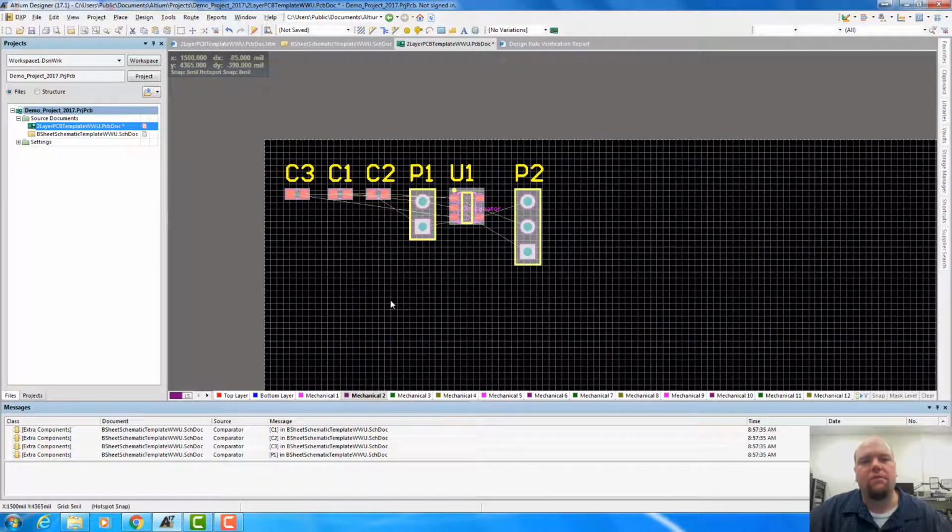Okay, so a lot of times the first thing we do with a board design is we move the components generally to the region we want them to be. For more complex designs, we might have a power regulator section, and all of those parts need to be in a certain area. We can create rooms for something like that. We're not going to talk about those in this video, but there are ways to specify in the software that all of these components must exist within this specific region of the board. But for now, we're just going to do this stuff manually.